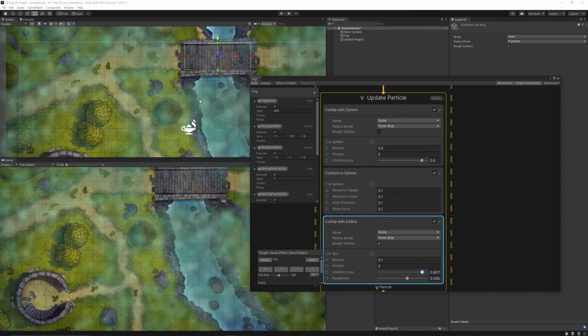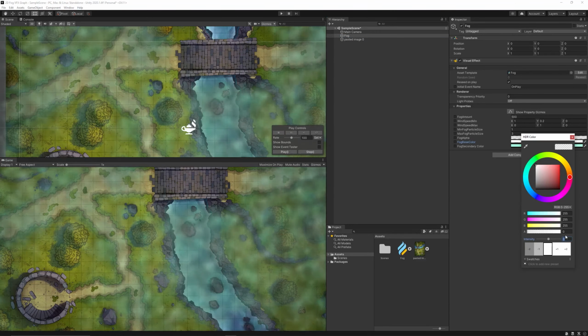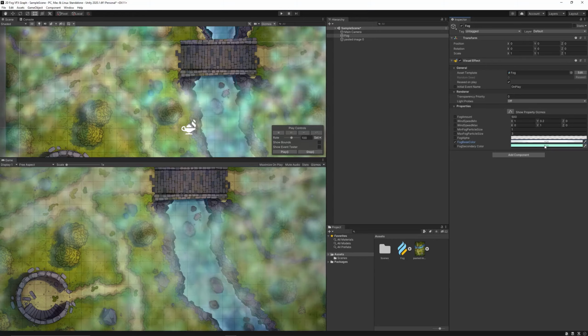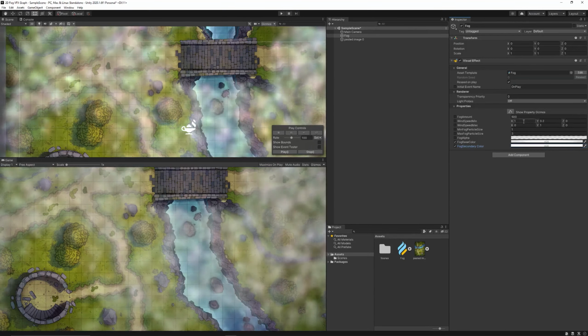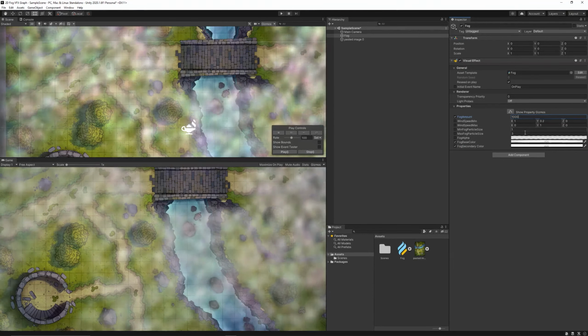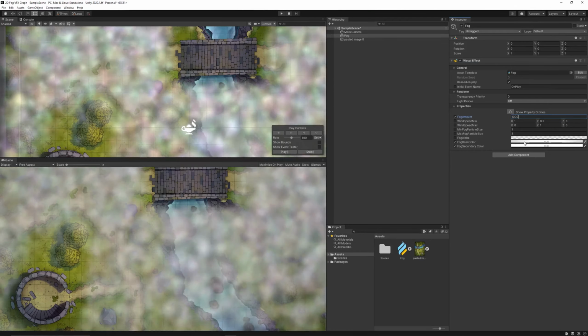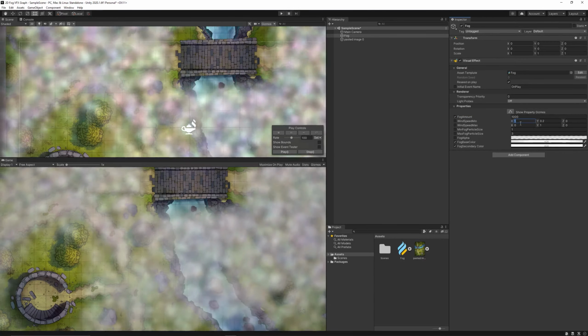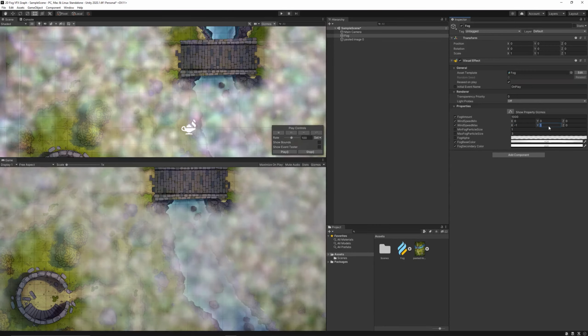And that's all. We can now enjoy adjusting the parameters we created throughout this video to reach the fog that suits our scene. So maybe let's increase the fog amount to 1K and change the wind speed to be something to top left instead of top right, maybe left down.